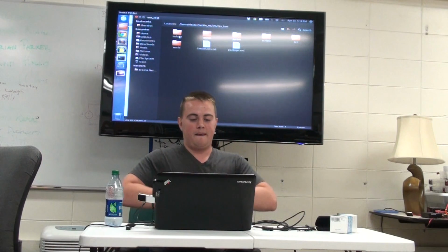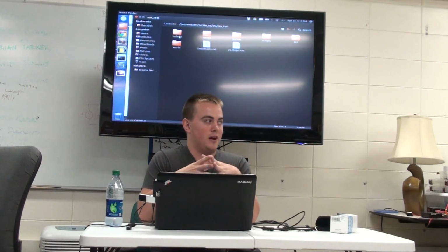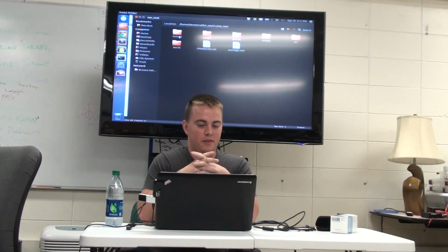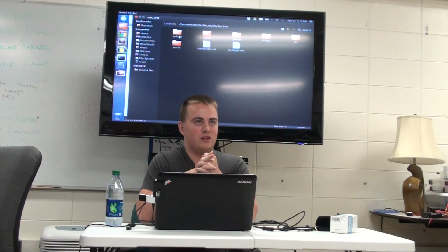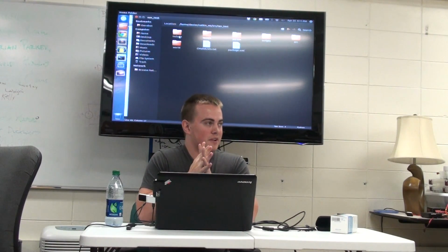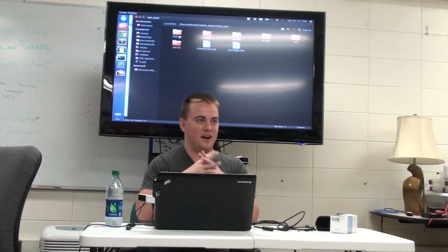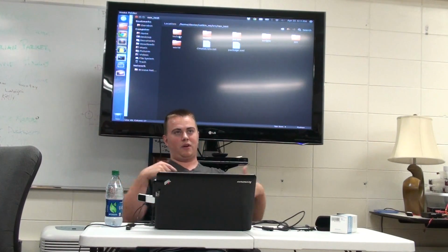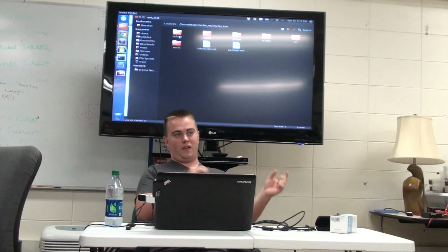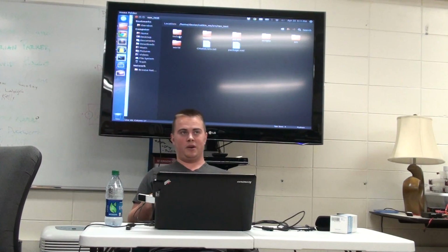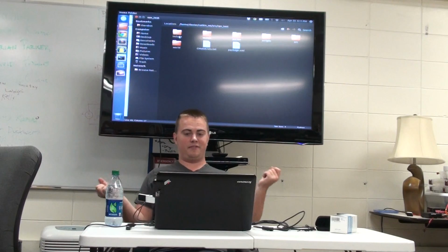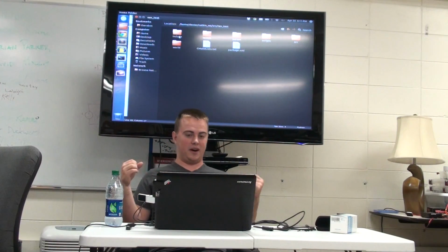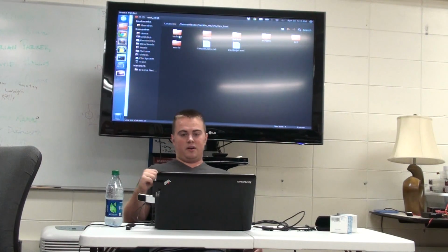Now that we have this program, we want a way to actually launch it, and the way you do that is via a launch file. ROS has its own system called ROS Launch, which lets you create file definitions for a list of things you need to launch at the same time. Then you can just call the launch file and it'll launch all your programs for you. It'll launch other packages. It'll do all sorts of nice stuff so that you don't have to go to the terminal and individually launch every single file.